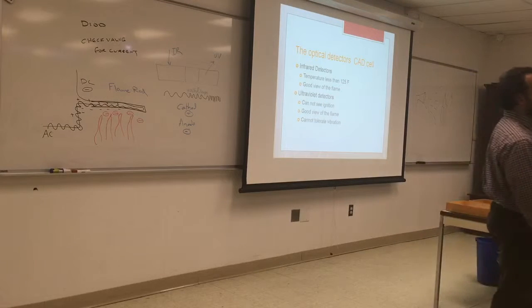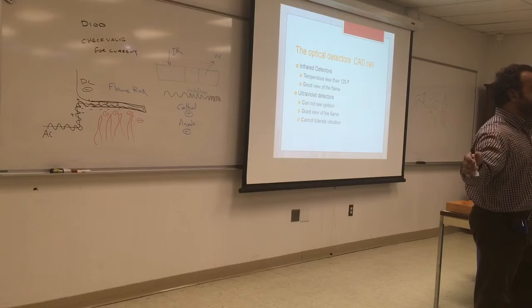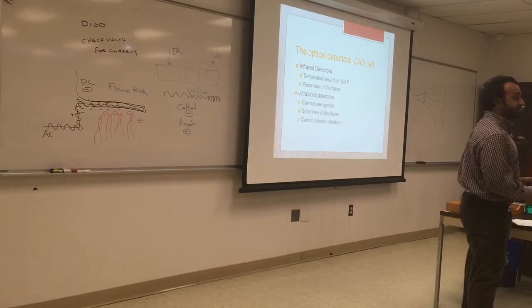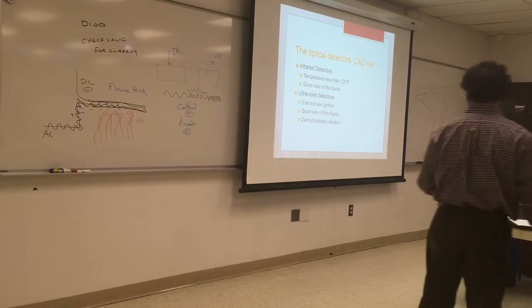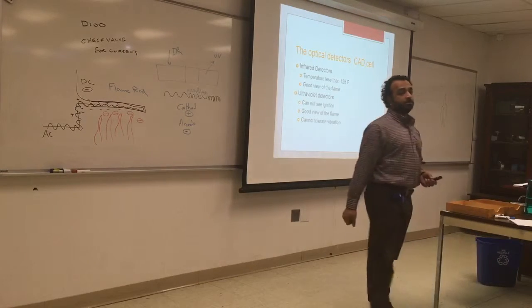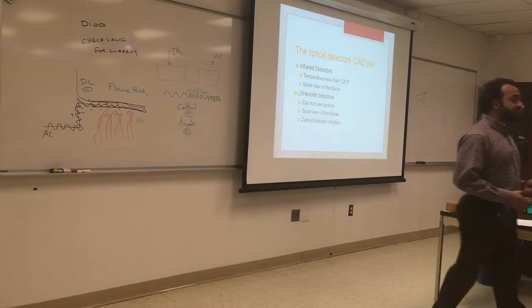In your car, for example, if you have an imbalanced tire, when does it start to vibrate? When you're doing 60 or 65. Then if you exceed that speed, it stops vibrating. So at a certain speed, the vibration becomes very intensified, and this is when you feel it. Why do you think it does that? It's something called the critical vibration, and it has to do with resonance.